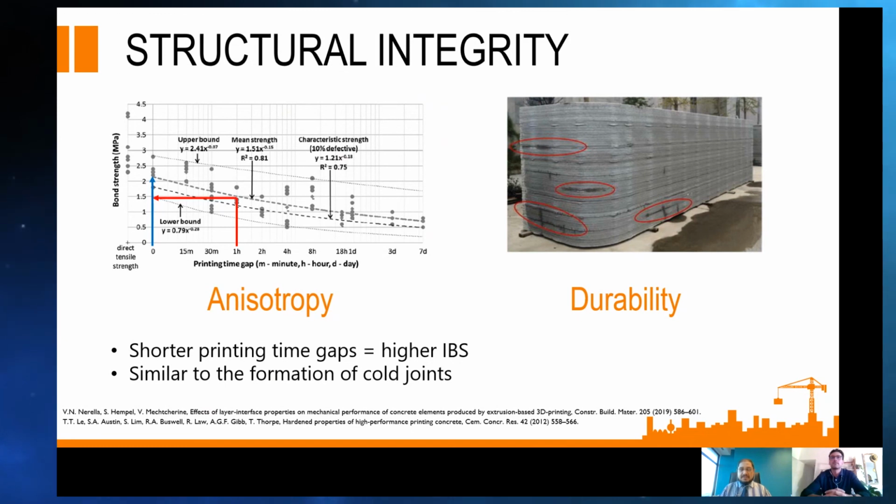And I take it the things like maybe installing reinforcing might be something that could mitigate against those other type of failures as well. Absolutely. So this would be the same premise as you would have in conventional construction. You would have a certain capacity, concrete's weak in tension, strong in compression. So obviously use the concrete as your compressive resistor, and then use your rebar as your tensile resistance in the components. Look, then also at the end of the day, it all depends on application, where exactly you are planning to make use of the product or the structure. Absolutely. So we will definitely follow the path that's been set out for us in conventional construction and design these components for the intended use. No, definitely. That's the engineering way of doing things. You design a thing that's fit for purpose and for what it's made for.